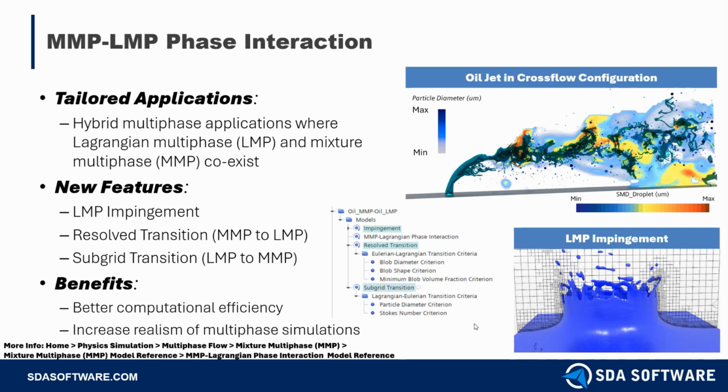With these new models, the MMP-LSI approach can essentially replace the VOF method in hybrid multi-phase simulations and help reduce the computational expense that was associated with the VOF method before. And as you can see in the bottom left corner, I have something called a more info path. That is there to help you find more information in the STAR-CCM+ documentation in case you are interested in learning more about this feature. Towards the end of the presentation, I'll go over how to use this more info path to navigate through the STAR-CCM+ documentation.